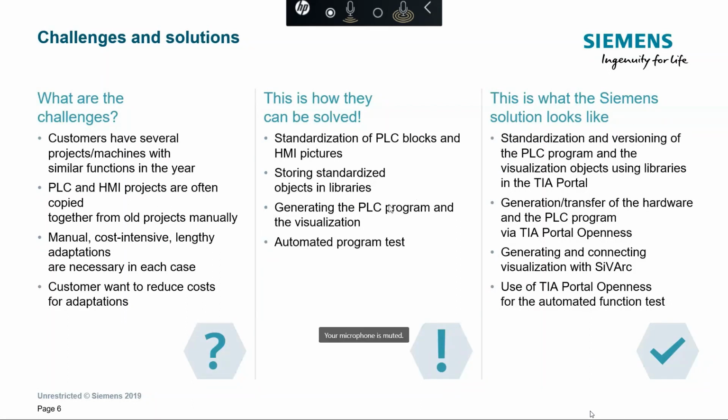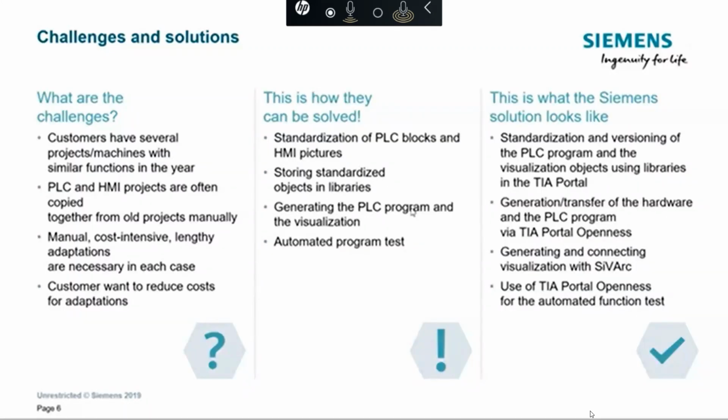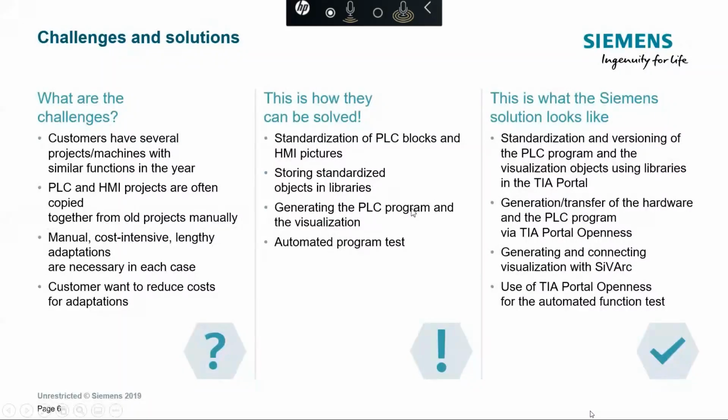I hope many of you might have heard the term TIA portal openness. What we mean by this is that the different actions or events that happen within the TIA portal platform, when we open the software, create a new project, add the systems, and compile the project, we could do all of these from an external software interface as well.